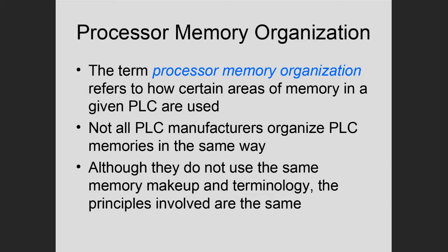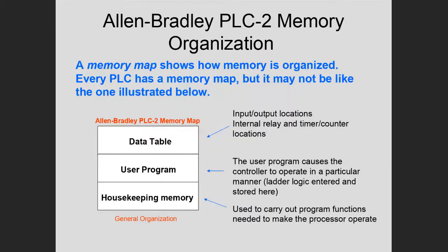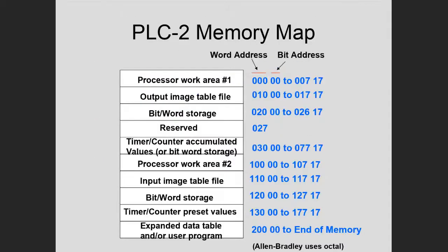How is memory organized? When you deal with digital devices that have memory, the term memory map comes up. All a memory map does is say how a memory is located, how it's divided up. Here I have 2 memory maps. I'm going to show you quickly. Here's one memory map, and here's another memory map. Basically, this memory map is for the Allen Bradley PLC-2, and it divides memory.